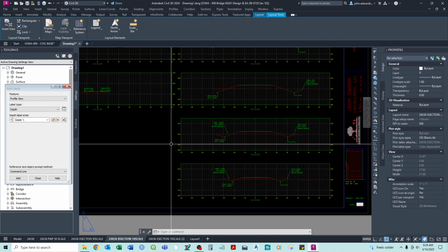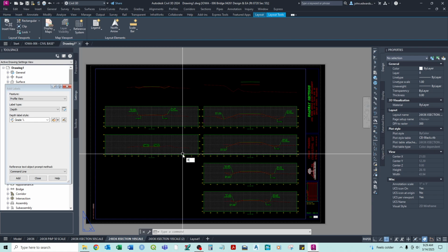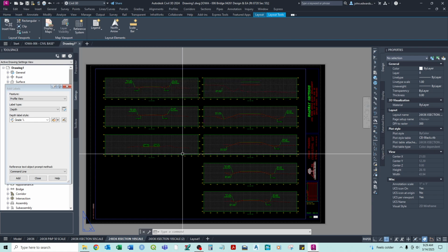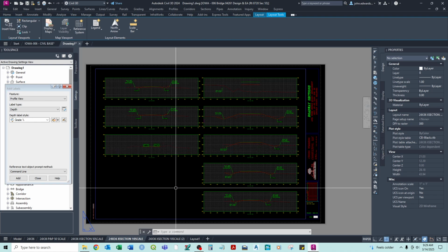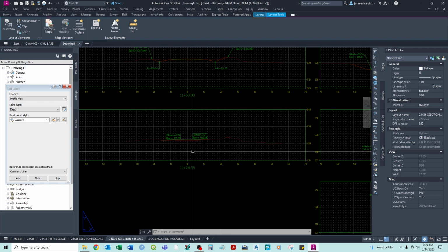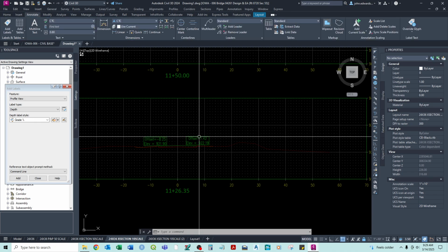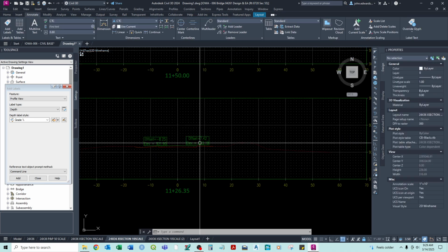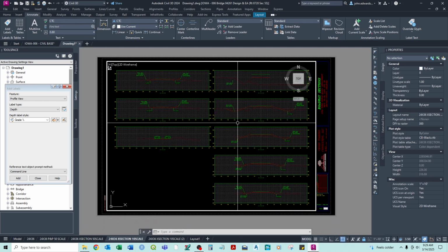So those are a couple changing the LT scale. So that's the line type scale. And the PSLT scale would be the paper space line type scale. So because that was off, and that's only between 0 and 1, the line type scale can change to a bunch of different things. So now we have all of our grid dots. Now, because this is XREF, we can't directly mess with the labels here, but we can add some, and this will work the same way.